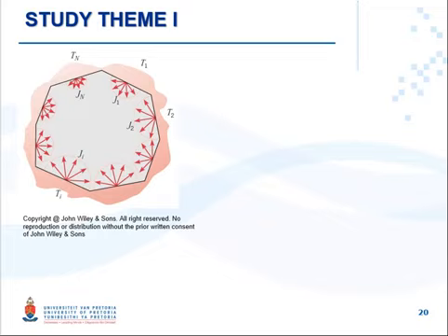We have an enclosure with n surfaces, and all the surfaces are radiatively active. The summation rule follows from the conservation requirement that all the radiation leaving surface i, or surface 1, whatever, must be intercepted by the enclosure surfaces, because there is no other way.